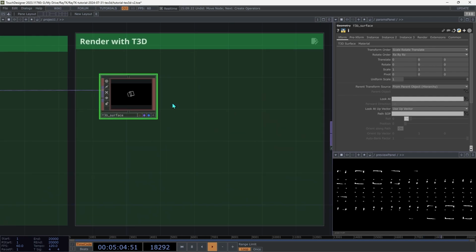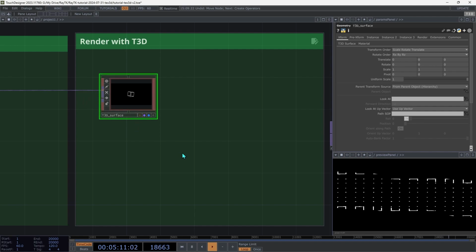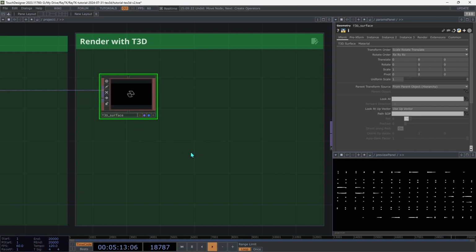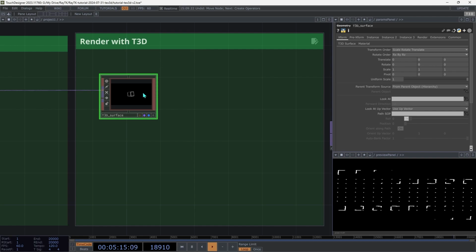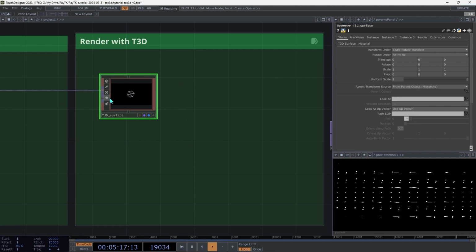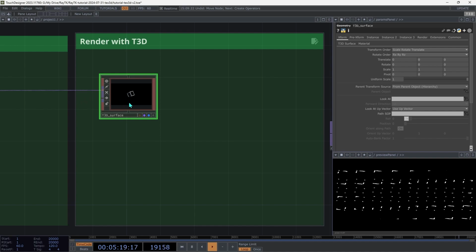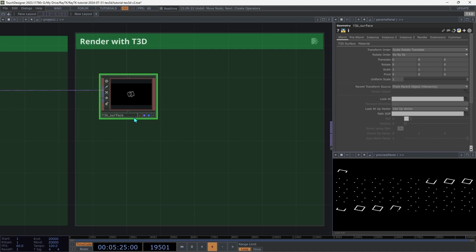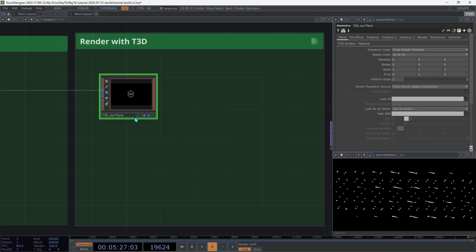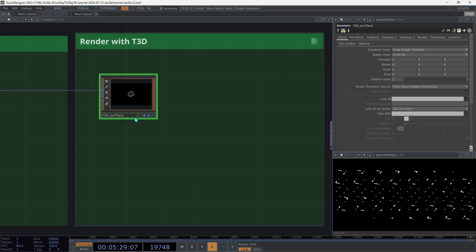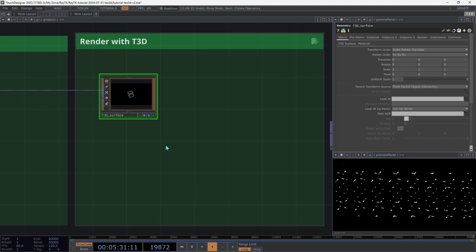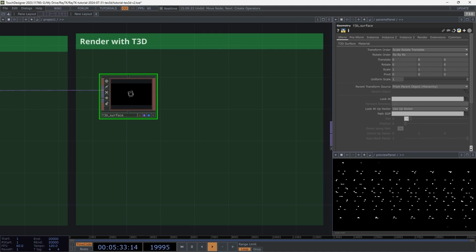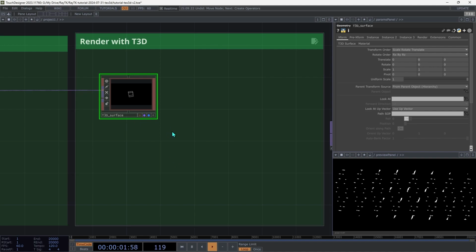This operator uses a clever trick to do ray marching, but within TouchDesigner's native rendering system. It uses a SOP cube that it places into space, and then as a material, it has a whole ray marching system built in. This is a similar approach to what the Fuse library for VVVV uses. I'll probably end up adding a similar technique to RayTK in the near future because it seems pretty handy.